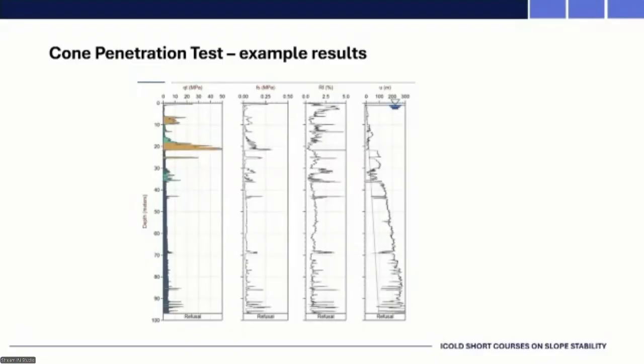And this side is probably quite useful. They know where the groundwater table is, so you've straight away got one point on that line, and probably by doing a few dissipation tests to an adequate degree of dissipation, they could determine the actual equilibrium pore pressure at many other depths. But what we're measuring with the CPT is effectively the dynamic pore pressure. So that U2 measurement is the dynamic pore pressure.